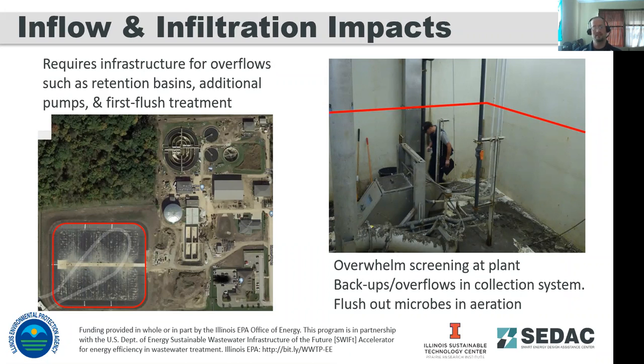for those plants. On the left side of the screen here, you see this was a plant that condensed 3 different wastewater treatment facilities into one regional facility. Because all those flows were coming to one place, they had to build, I think this was an 18 million gallon stormwater retention basin highlighted in red there. It's a whole extra capital cost that maybe if there was a pre-existing I&I assessment on their system, they could have invested that into reducing flows coming to the plant.